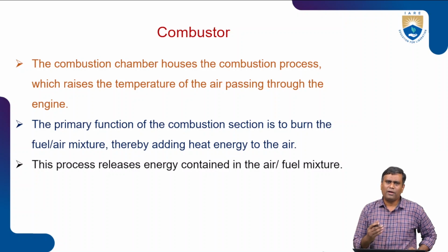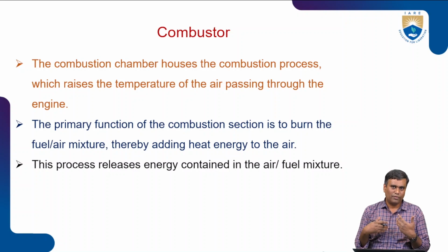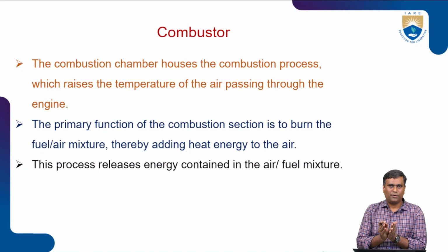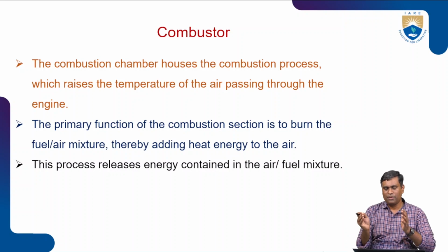So overall the purpose of the compressor is to raise the pressure, so that combustion of fuel will take place more efficiently. That is the purpose of the compressor, right? But in between, the diffuser will be there. That is to make sure that proper combustion takes place, proper mixture and burning of the fuel and air combination.